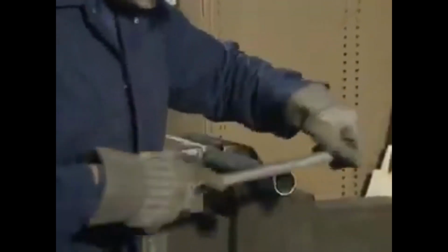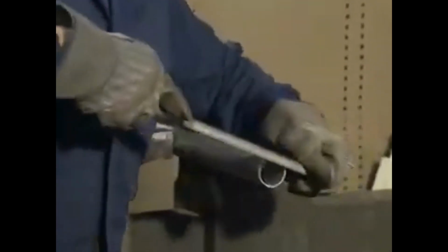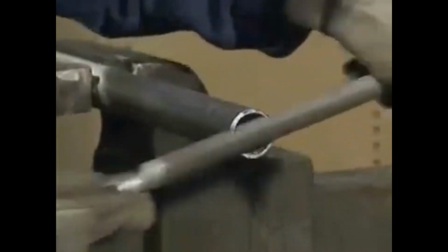Sliding friction occurs when one surface slides across another. This type of friction offers the most resistance to motion, so machines are usually built to minimize or eliminate it. One way of building a machine to minimize sliding friction is to place rolling elements between the moving surfaces. This is the principle behind rolling contact or anti-friction bearings.